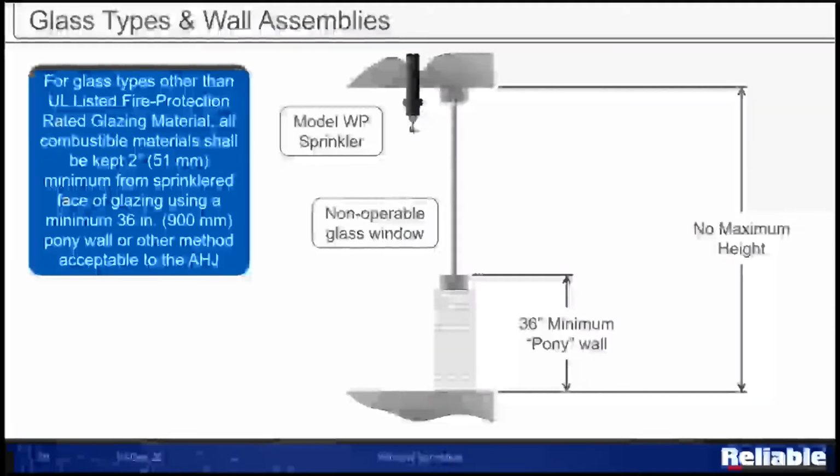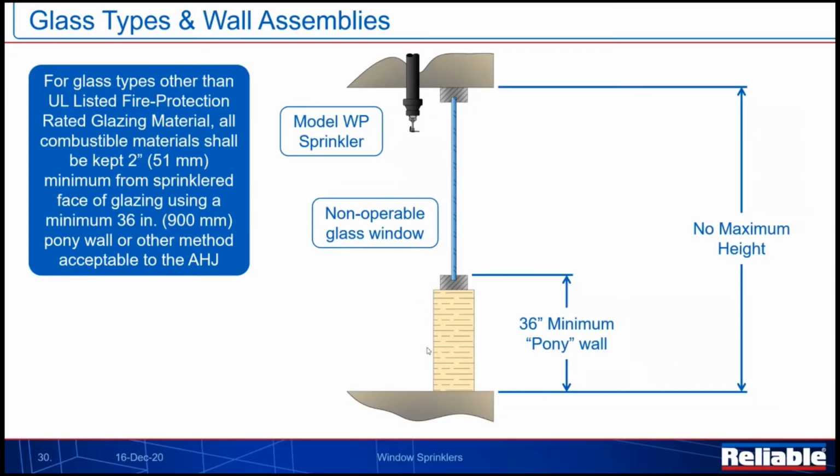And what ends up happening is when a fire occurs down here, a small, tiny fire, the heat generated by that fire gets absorbed by the adjacent glazing material, and it gets superheated. And by the time that waste paper basket generates enough heat to activate a sprinkler, which could be 13 feet in the air, it's going to activate, discharge water on this glazing material, and it's going to be shocked thermally